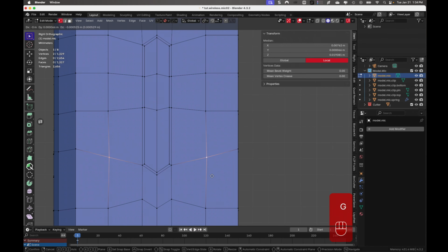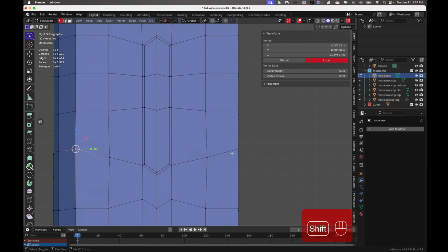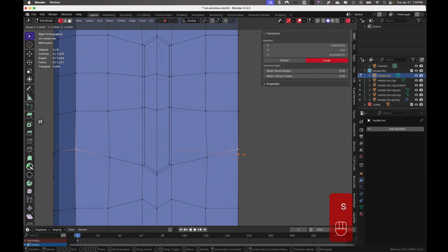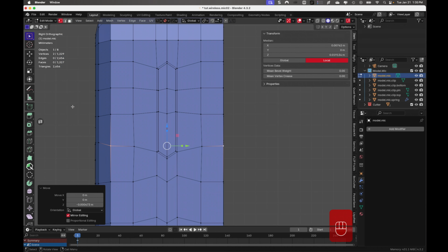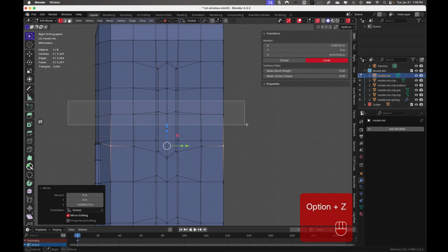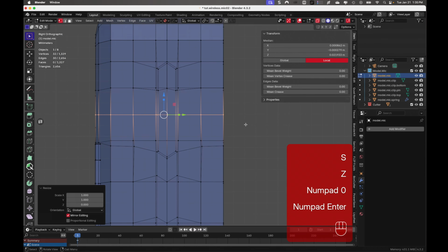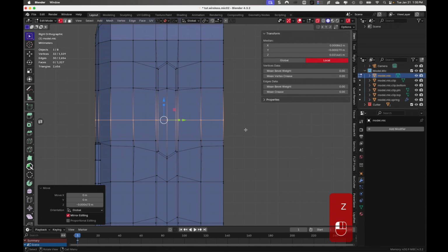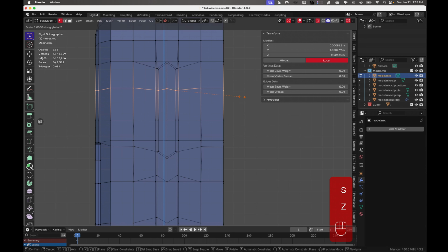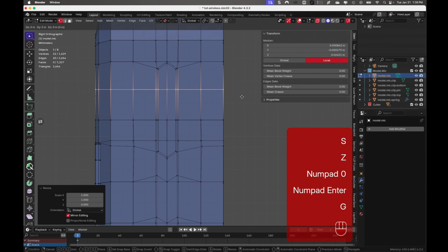And I'm just relaxing out some of the verts here for the geometry, so they don't run any risk of any kind of tessellation issues. Not that we would. I mean, we got about 50 miles between these vertices, so I think we're good. But just to be safe. And some of these I'm just going to straighten up, like this one, and then the one up above it. I just want them straight.